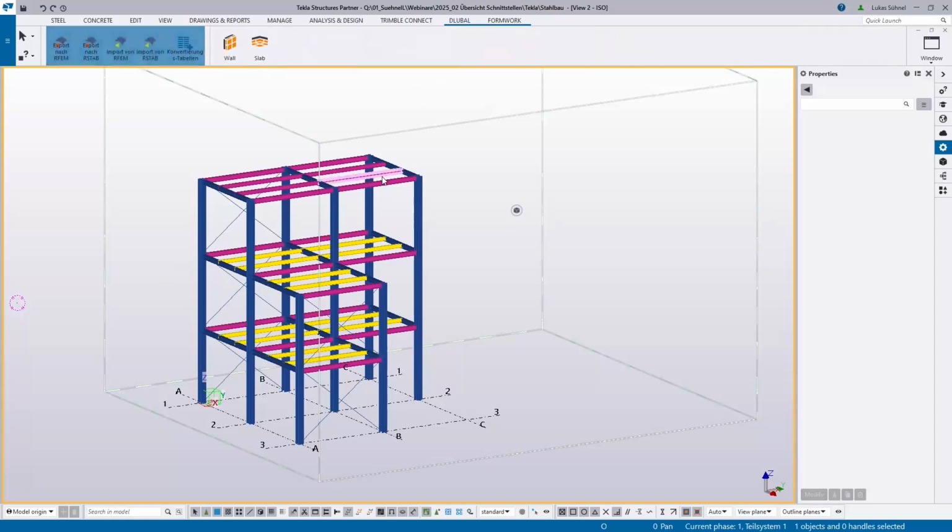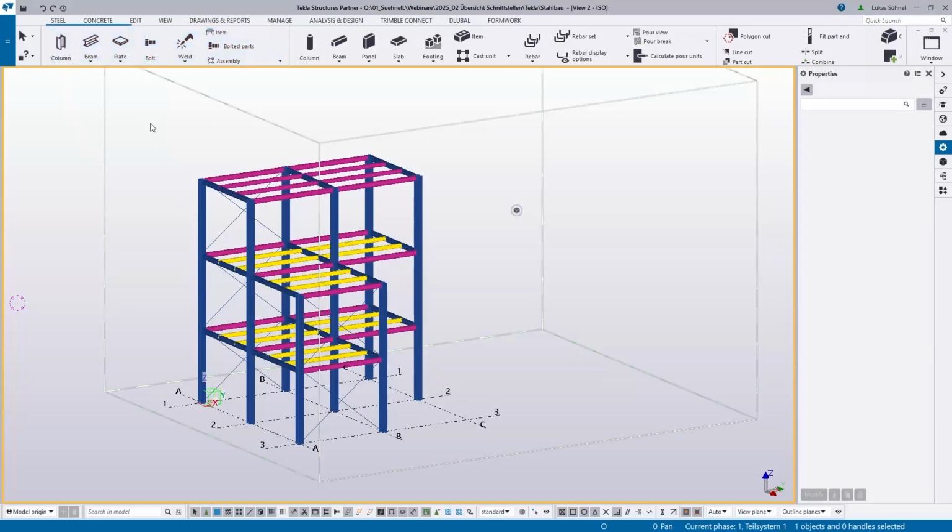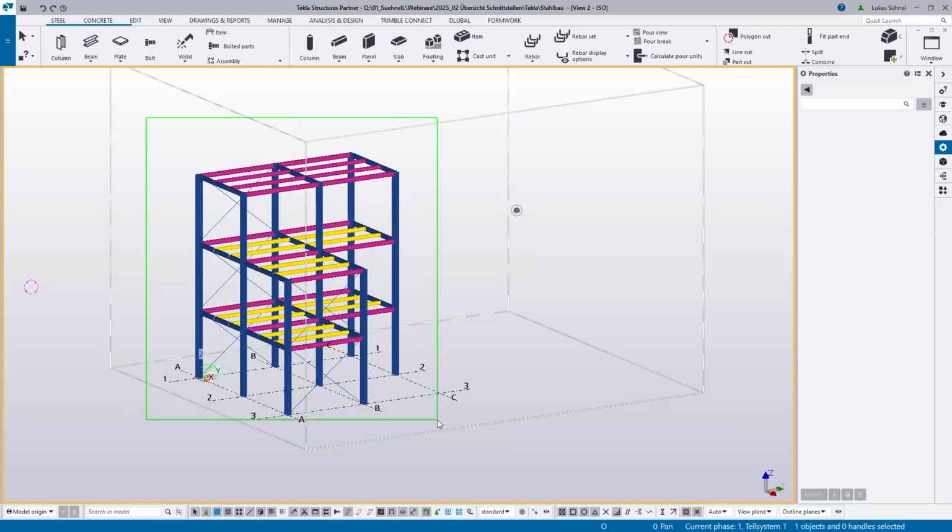And then you can ask, why would I use Tekla? We have the direct interface for that, as you can see here. Yes, that is true. We have a direct interface. It's working quite well. But a direct interface always requires both programs on the same PC. So you need to have Tekla and RFEM on the same PC. That is not always the case. And then a file format for the data exchange would be quite handy. And we have that for Tekla. And I want to show how you can do it.